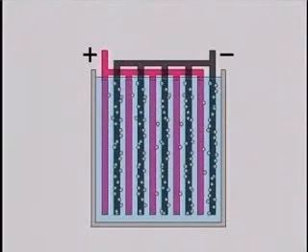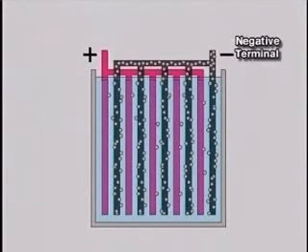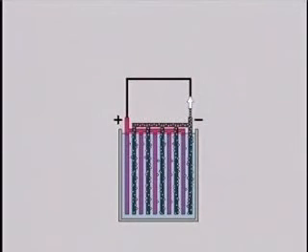The negatively charged electrons collect on the negative plates, giving that terminal a cumulative negative charge or potential, thus the name negative terminal. As the electrons migrate away, the other terminal develops a positive charge or potential and derives its name, positive terminal. If a path of conductor material is established between the terminals, the excess electrons at the negative terminal will force a flow of electrons through the conductor to the positive terminal.